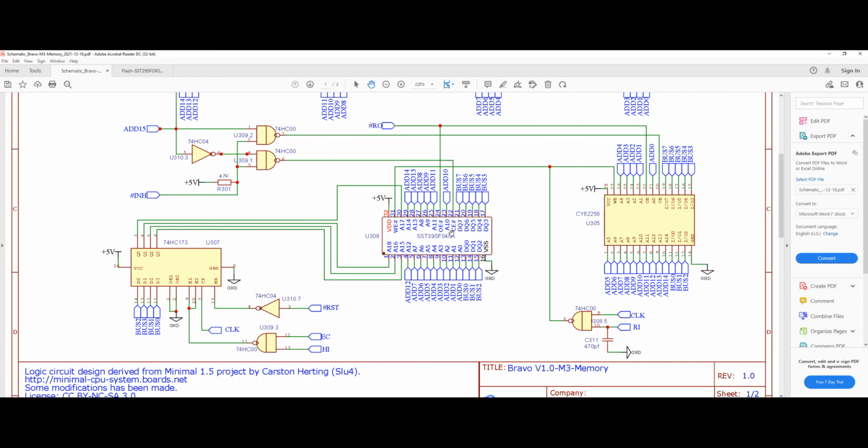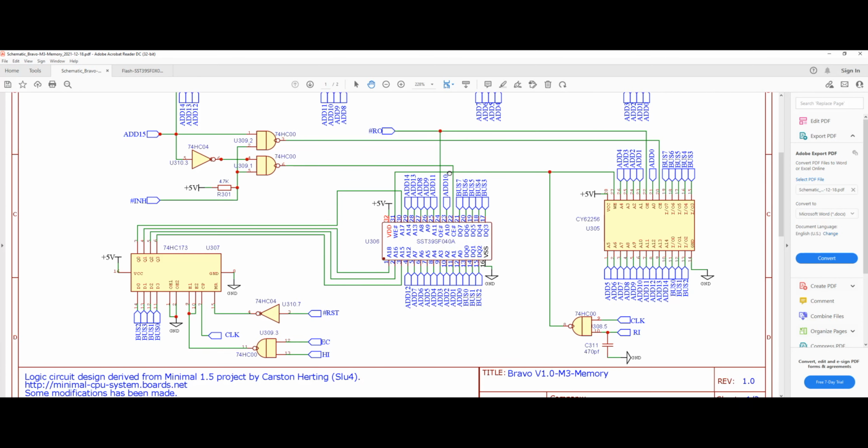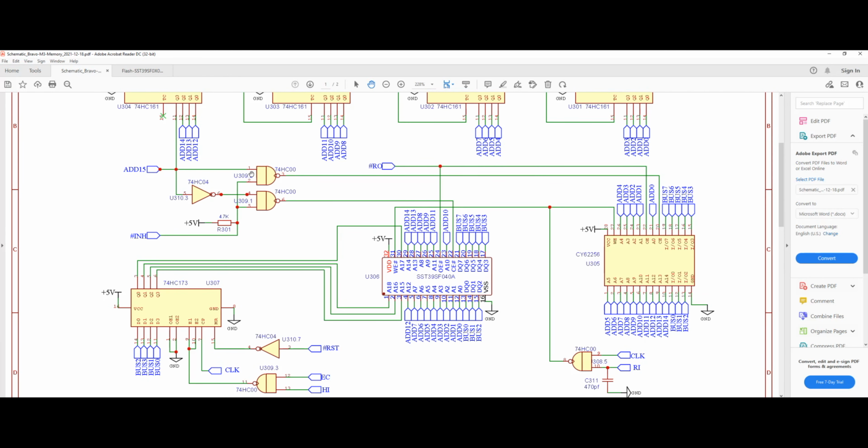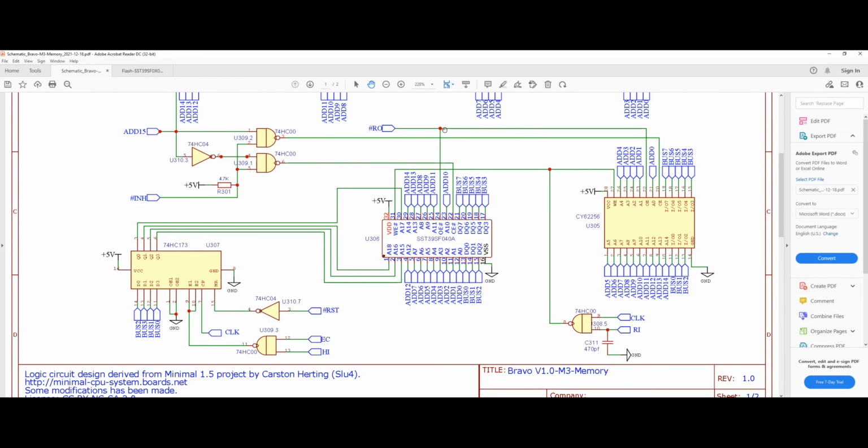The other signal is the chip enable, which again, we talked about in the previous video. It is just an active low signal connected to pin 22 to select and enable this chip, which again is connected to our chip selector circuit that we talked about in the previous video. So that should be quite clear now.